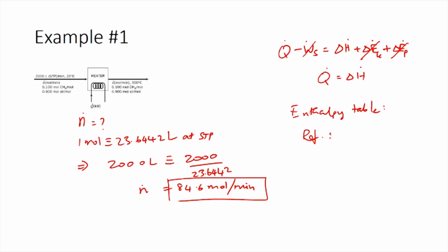Here we have two components, methane and air. Identifying appropriate reference states is crucial for performing calculations in a simpler fashion. As I had already mentioned, combustion gases such as air, oxygen, carbon dioxide, carbon monoxide, which are involved in combustion reactions, commonly have a table where you can get enthalpy data from.